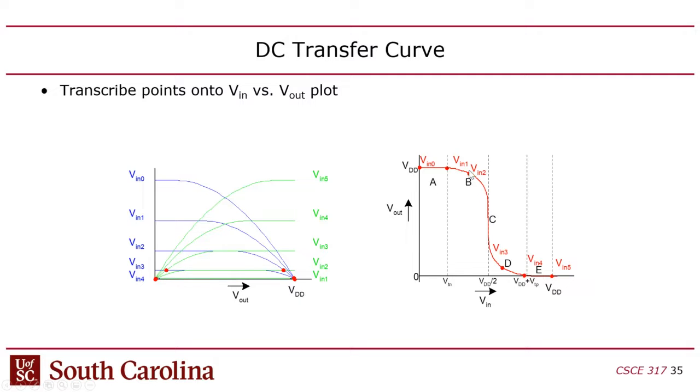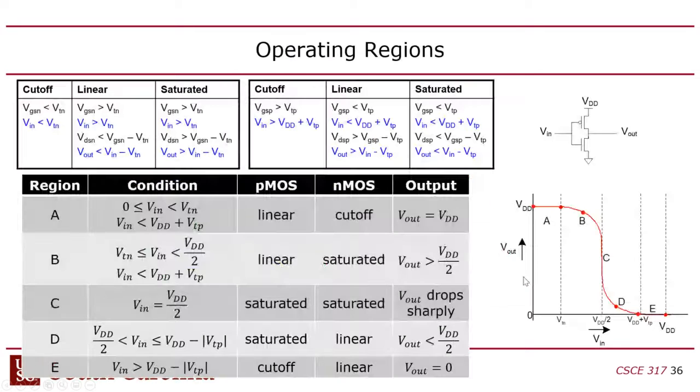Now you might say, okay, now I'm starting to see that you're basically characterizing the gate, right? You're looking at the shape of the output and the transition. So what is the point of all this? Well, hopefully you're starting to see that the point of all this is that we're measuring the performance of the gate. We're starting to get a picture of how fast the chip will run, essentially. Now this is just internally inside the gate. We're not considering other factors yet. But this is the shape of the output of the inverter.